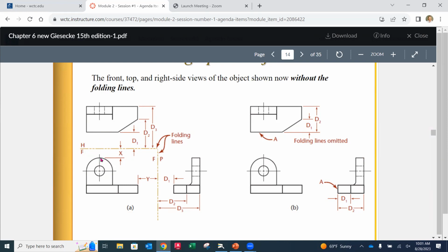So I really wouldn't see the hole at all, but I'm going to recognize and say there is a hole there. So we will put it in and reference it in terms of hidden lines. A hole in the view where it's not seen as a circle will be represented by the width of the diameter. So you'll notice that this, what we call the quadrant on one side, and the other quadrant is then going to be the line view to show us that part on the upright where it's going through.